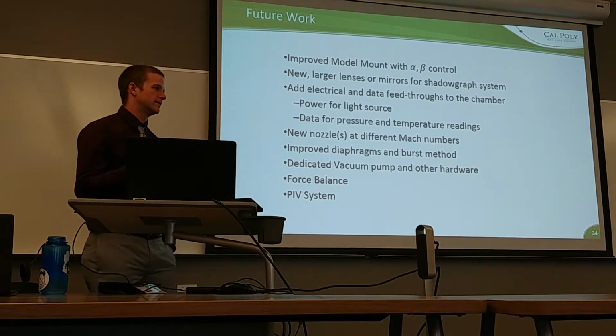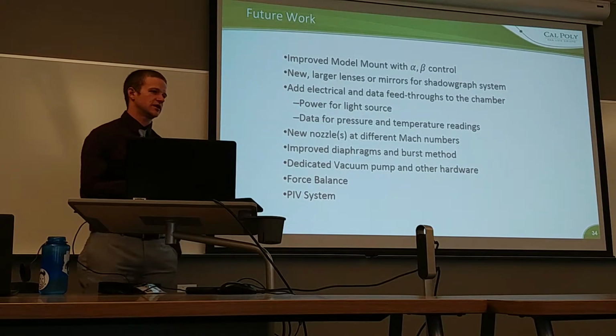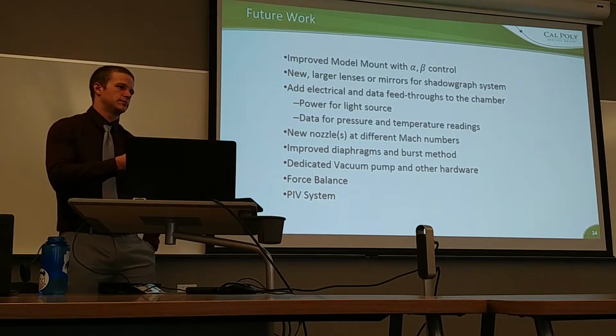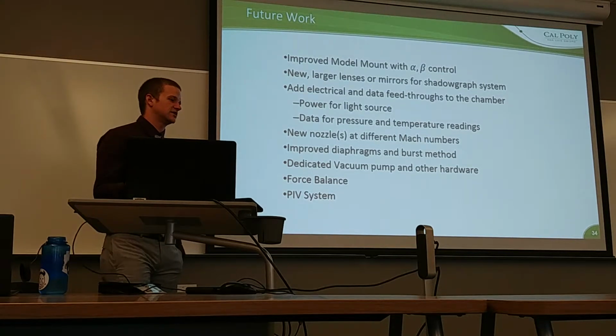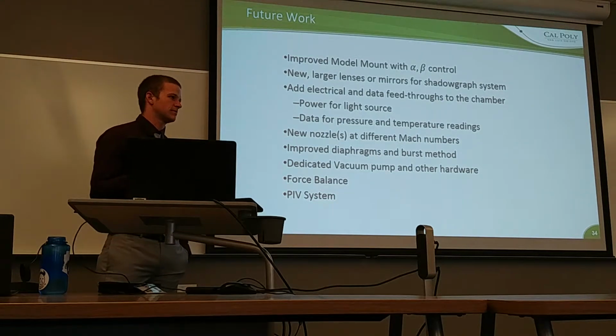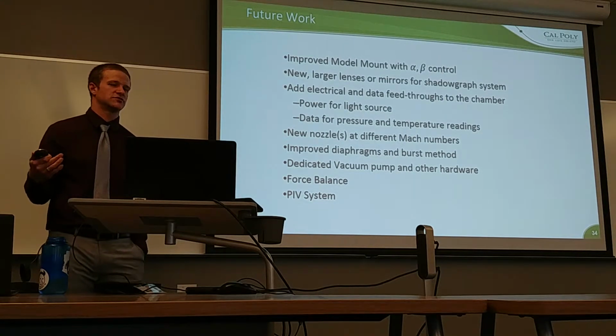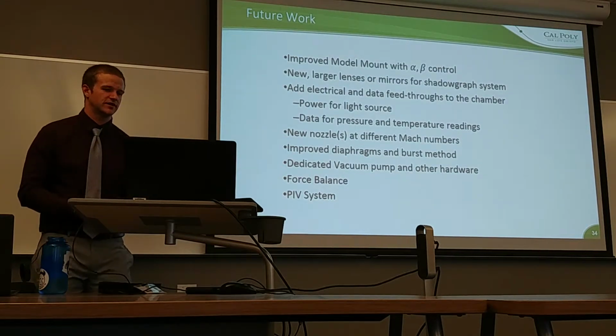Because the flow is supersonic, the pressure in the chamber is incapable of affecting the conditions at the throat and through the nozzle, because the rate at which pressure information propagates through the flow is Mach 1 and the flow is going approximately Mach 2.5.